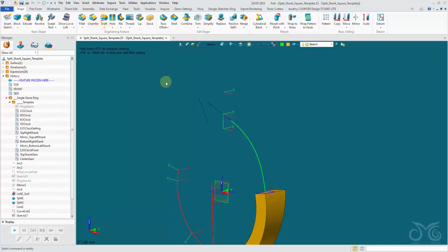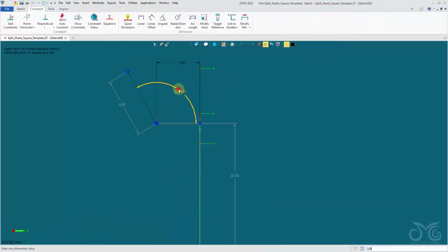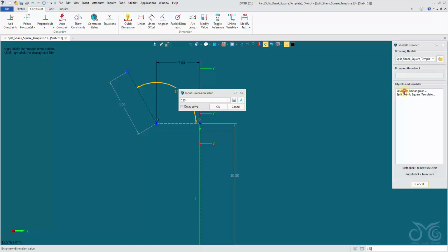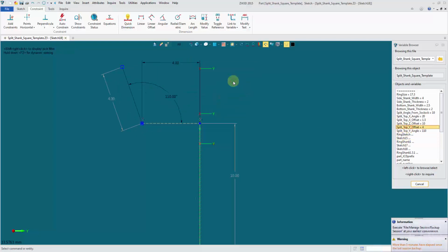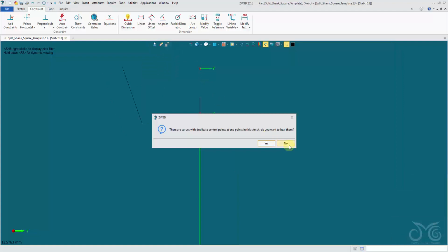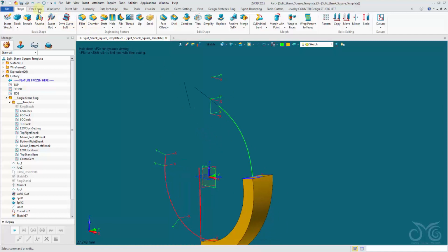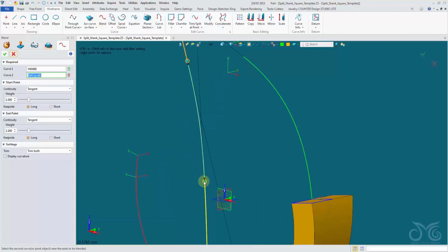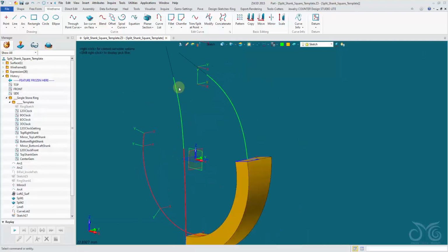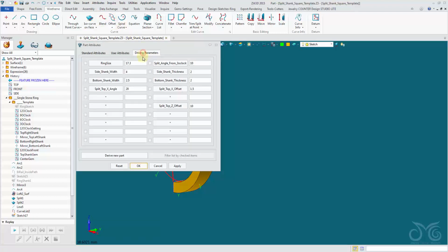Right click, let's edit our sketch again. Link these up, we had the Y angle and the Y offset. Okay, now let's perform our blend again. Wireframe, blend between these 2 points. There's our second curve. Let's add our attributes into our driving parameters.